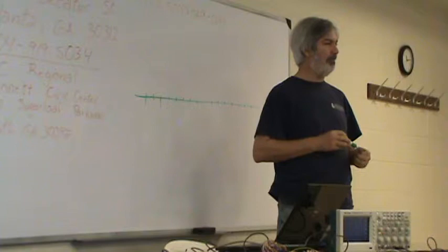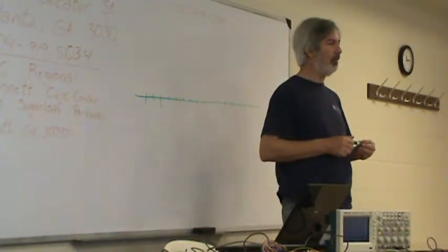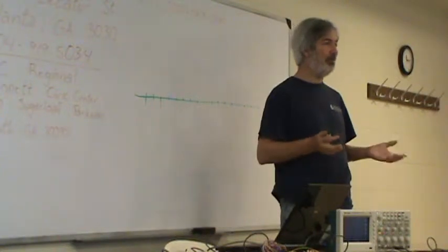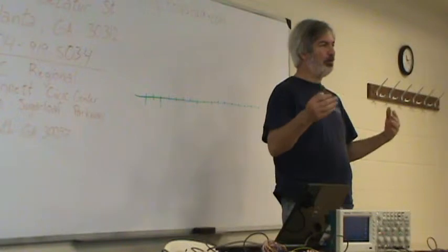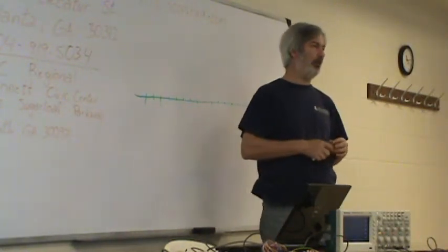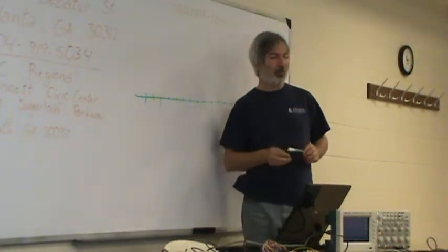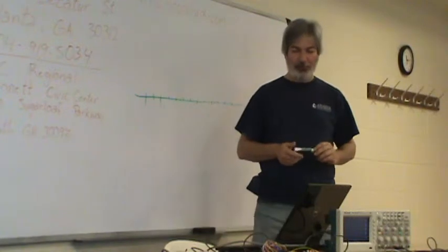In general, a lot of documentation for devices isn't always perfectly clear on which pins transmit and receive. And it's like, okay, you've got two devices, which transmit goes to which receive, and you want to make sure you get those right. Fortunately, most devices, if you get them backwards, they just don't work. They don't blow up.